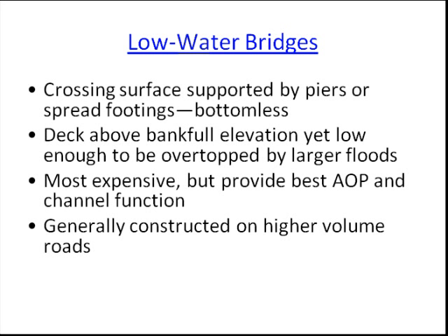crossings I've covered today. Because they're used in larger streams and intended to be overtopped by large flows, low water bridges can be fairly robust and require a lot of excavation and concrete work. Given the costs involved, they're generally used on higher volume roads and are an attractive alternative to conventional bridges. Low water bridges need to be outfitted with some form of railing or curbing for safe vehicle and equipment passage because they're usually lumped in with standard bridges in the permitting context.